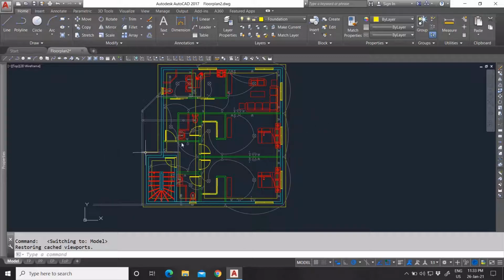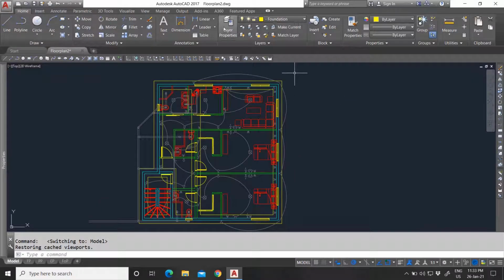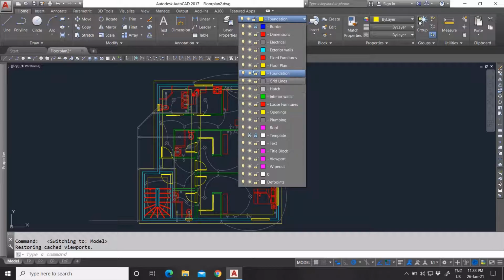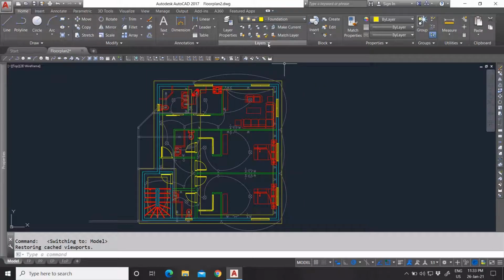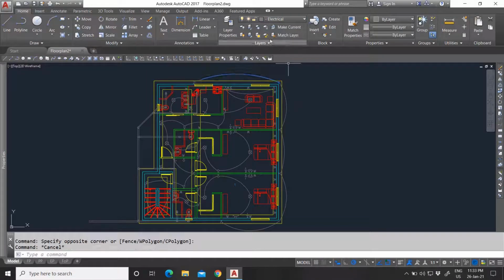I am just a pro for manually doing things, as opposed to leaving things to be done automatically by AutoCAD or the program itself. So that was it, guys, for layers, the layers panel. I hope you learned something. It was very in detail. I have never done a video about layers or used all of these buttons myself. As I said, by just going down on the drop down menu, you can always freeze and turn off layers. These are very handy to know, but 90% of the time you're just going to select the object and freeze the layer from right here, or make it invisible or lock it. Basically it does the same things as these right here.